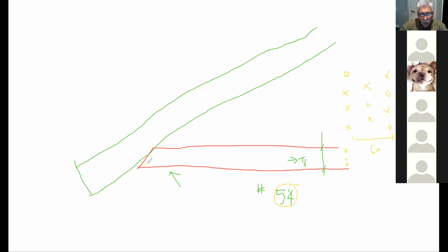So you know that from here to here, you have to maintain at least 40, right? And then here you have an edge distance of at least 13. Now, of course, if you work out your geometry, that means here you have another 40.